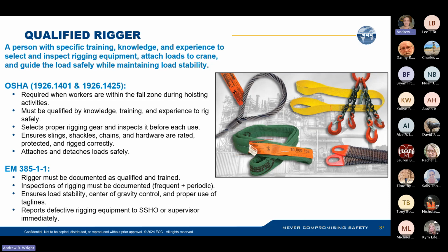They need to know how to select the proper rigging gear and inspect it before use and know when to red tag it. They need to ensure slings, shackles, chains, and other hardware are rated for the application, protected, and rigged correctly. And they are responsible for attaching and detaching the load safely and for using tag lines.